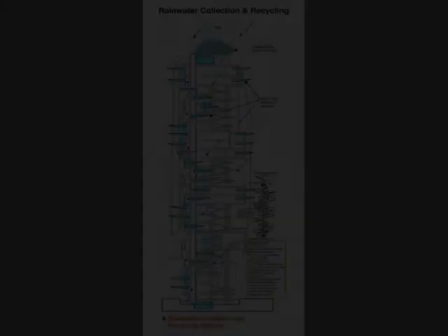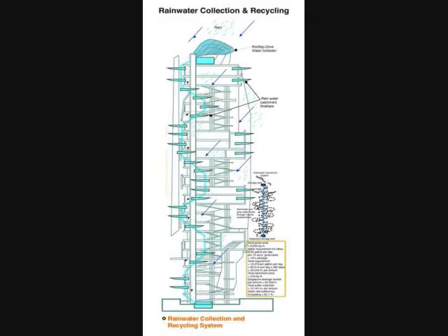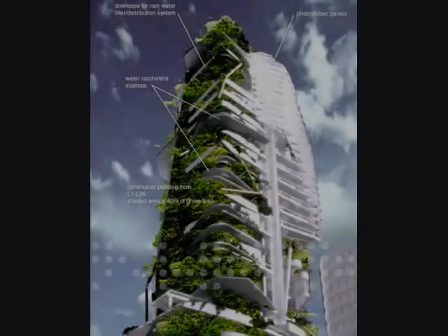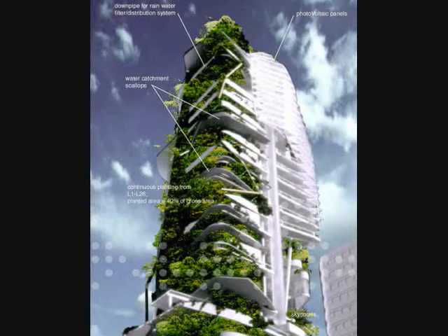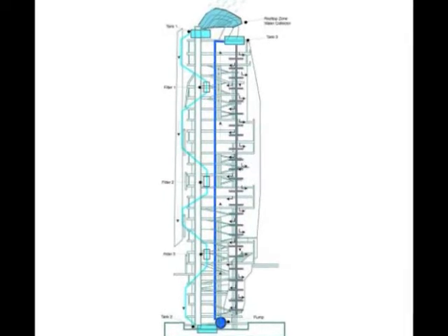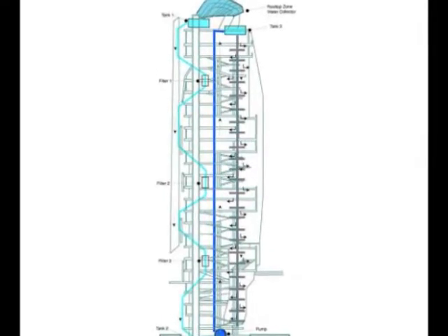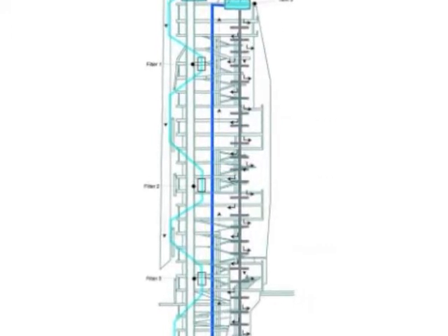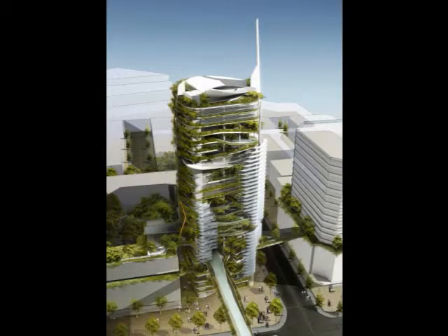Water recycling. Water self-sufficiency by rainwater collection and rainwater reuse in the tower is at 55%. Water purification. The rainwater collection system comprises the roof's catchment and layers of scallops located at the building's facade to catch rainwater running off its sides. Water flows through a gravity-fed water purification system using solid-bed filters. The filtered water accumulates in the basement storage tank and is pumped to the upper-level storage tanks to be reused, for example, for plant irrigation and toilet flushing. Mains water is only used for potable needs.